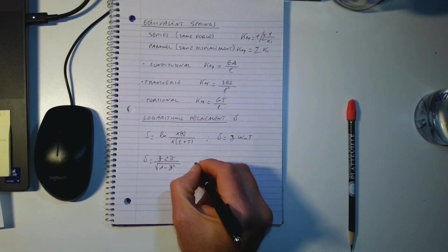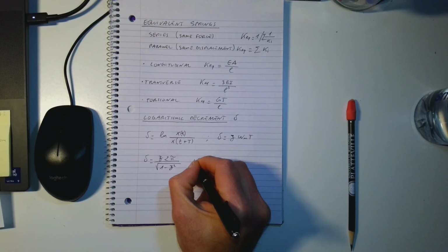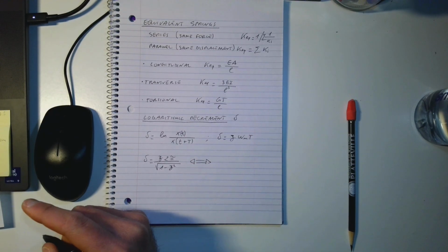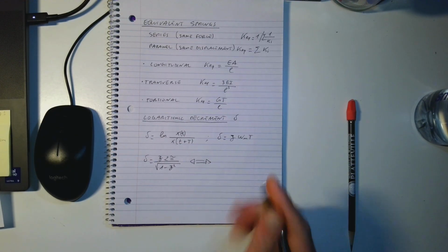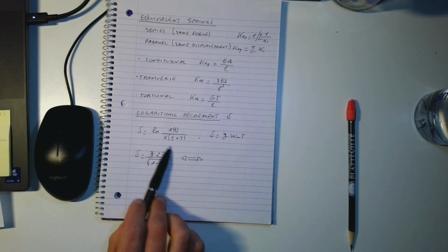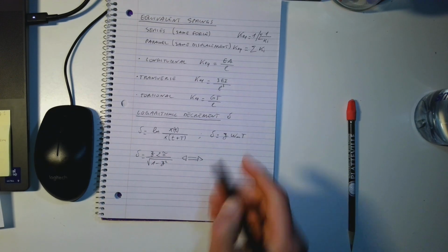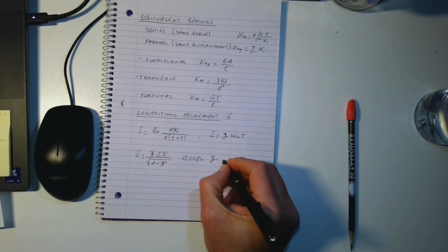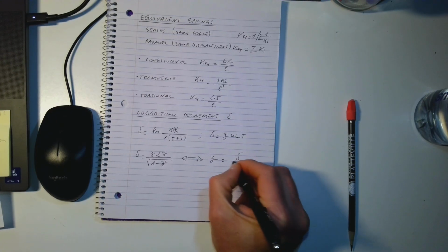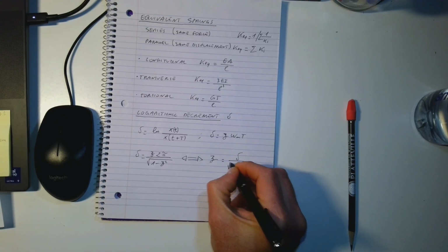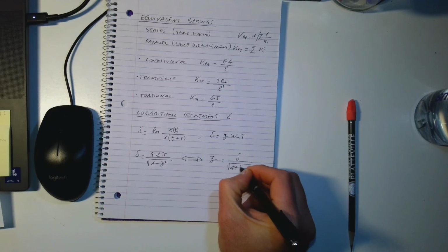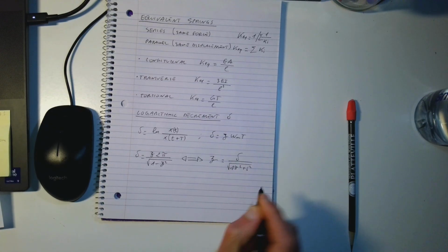As we said before, our goal is to find the properties of the vibrating system from the response, which means that we have to rearrange this expression here. So we have that zeta is equal to delta divided by square root of 4 pi square plus delta square.